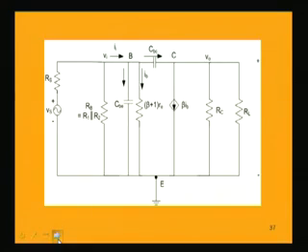So, let us revisit that circuit again. In this circuit we are now going to distribute this capacitance CBC in the input and output circuits. For that we have to find out the impedance value of this CBC and then correspondingly we can distribute it into the two sides, input and output, if we have the ratio of the voltage, that is k.